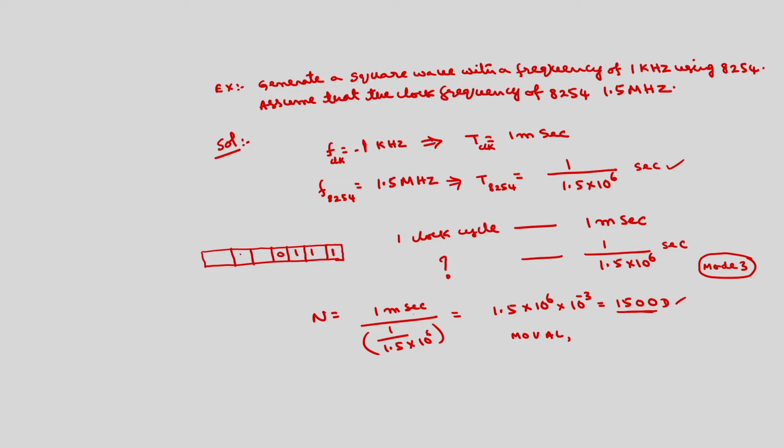So, this will be 1 1. 0 0 is latching, 0 1 is lower order 8 bits, 1 0 is higher order 8 bits, 1 1 is 16 bit. In that, first it will load the lower order 8 bits, then it will load the higher order 8 bits, and this is select counter. I can use any counter. Okay.